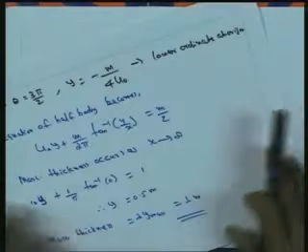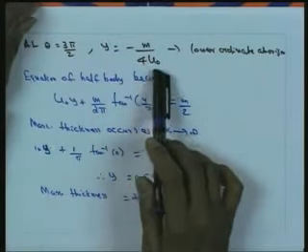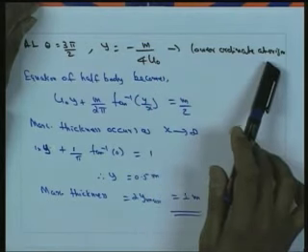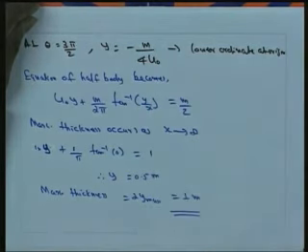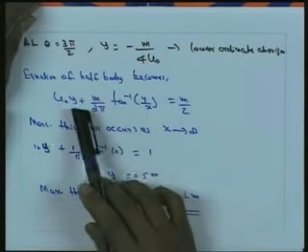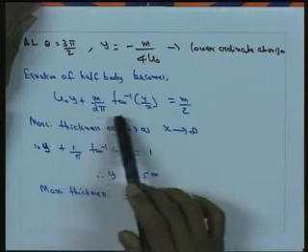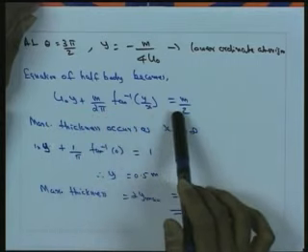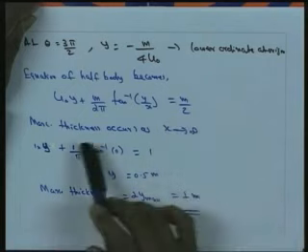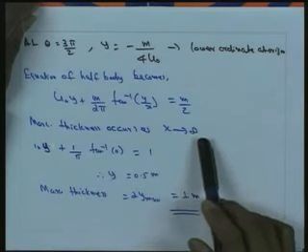So, at theta equal to 3 pi by 2, y is equal to minus m by 4 u0, which is the lower ordinate at origin. So here the lower ordinate at origin is y equal to minus m by 4 u0. So now the equation of half body becomes u0 y plus m by 2 pi tan inverse y by x is equal to m by 2, and then the maximum thickness occurs as x tends to infinity, which is the maximum thickness.